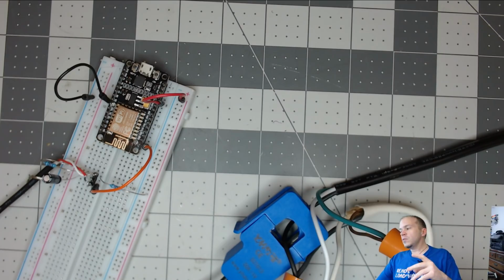So on the NodeMCU or the Wemos, it's going to be a little custom sketch. You will not be able to use Tasmota or ESP Easy, etc., that I know of, and some of the others. They just don't read that A0 pin quick enough to read the AC voltage and pull out the amperage that's being pulled over. But it does work.